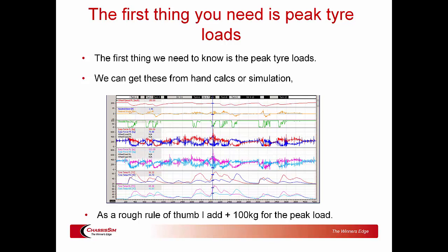Now, in that tutorial, creating tire models from scratch, which I talked about in an earlier Chassis Sim tutorial, your first port of call is looking at your tire loads. You can look at that either using track data or using the Chassis Sim track replay facility. It really doesn't matter what you do.